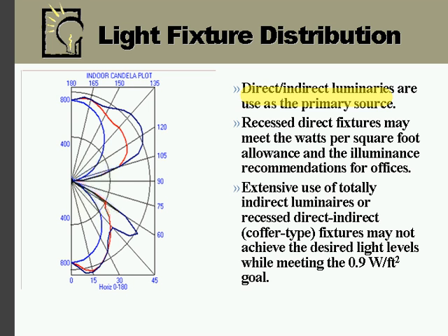There's a lot of different options out there for light fixtures. This was the committee consensus for a good energy efficient light source. It's going to provide good lighting in a space. There's problems if we use lens fluorescent fixtures on computer screen glare. There's problems if we solve the issue by using parabolic fluorescent fixtures, that they can cause high strain and glare in people's glasses and very harsh shadows. So there's pros and cons of all different types of light fixtures.